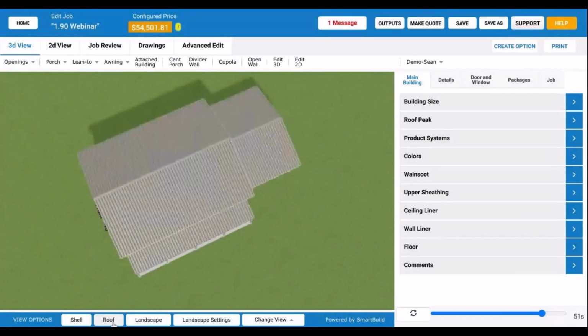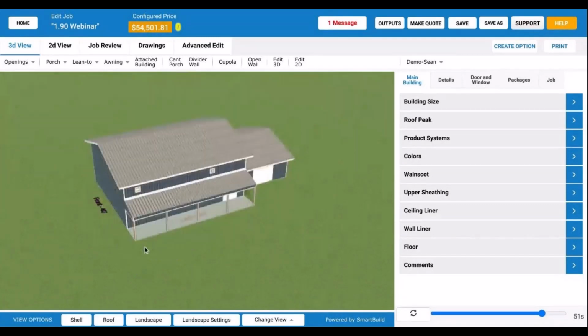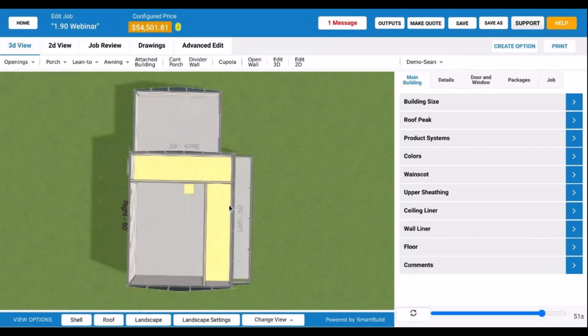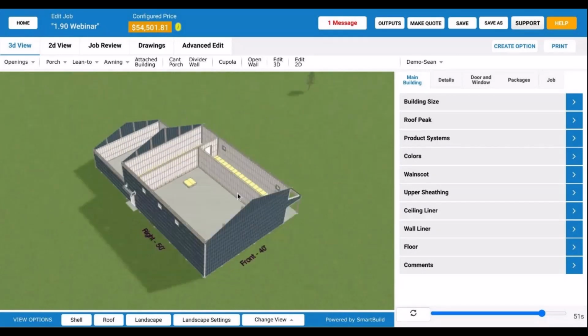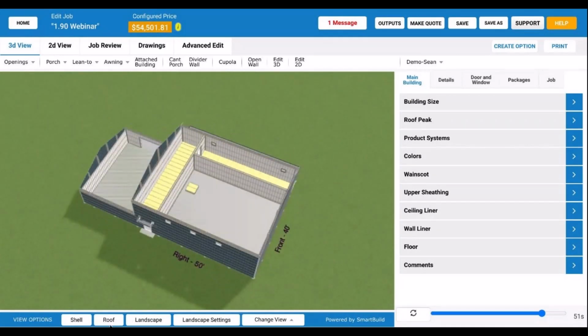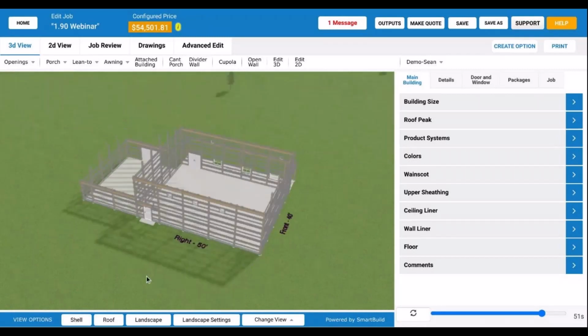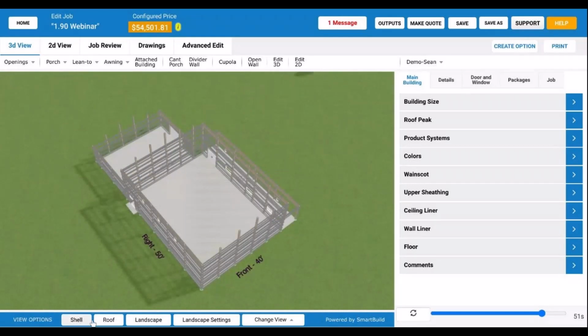And then if I click it one more time, we're going to be back to the start. And so there's our stair floating out there. That one's on a different level, so it's another click here to get rid of that one as well. So you can toggle through your different levels, your different floors, including the roof, depending on the visibility you want. And all the other visibilities are going to be the same.